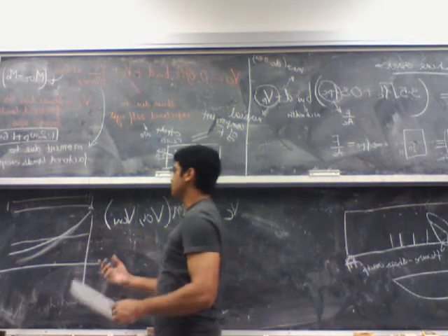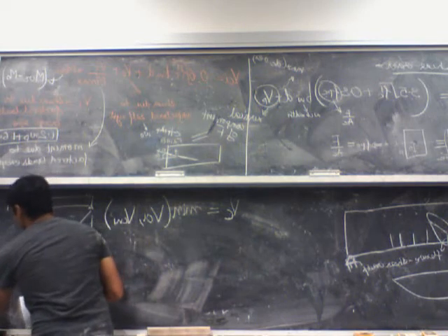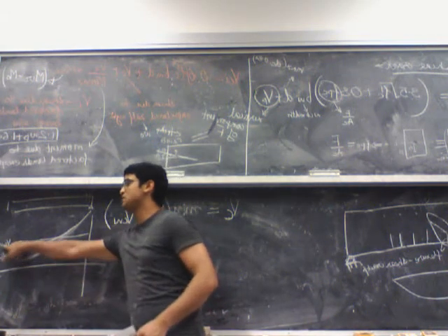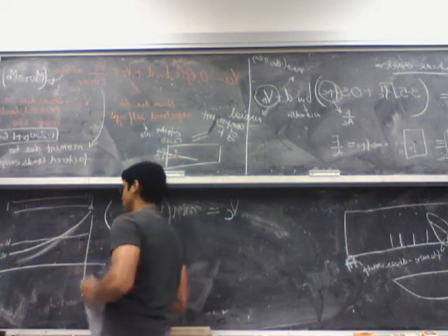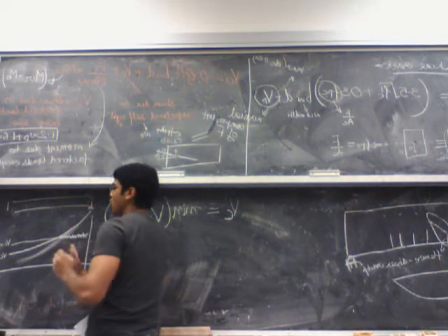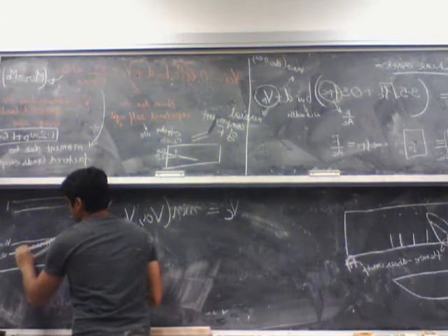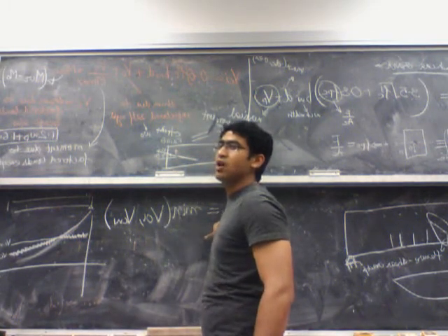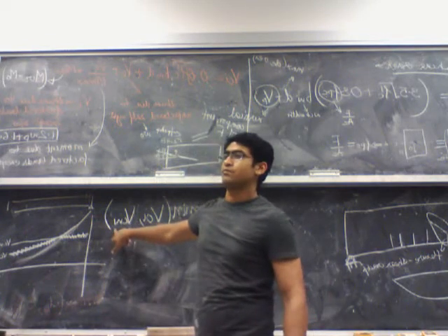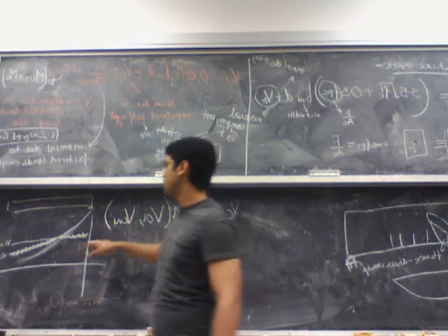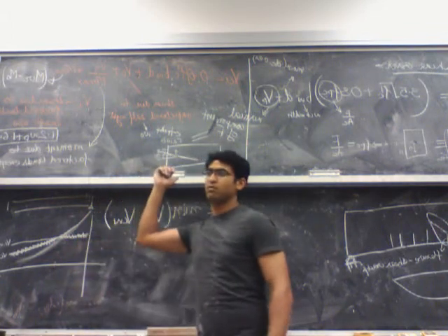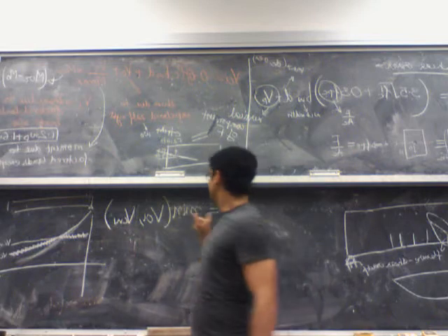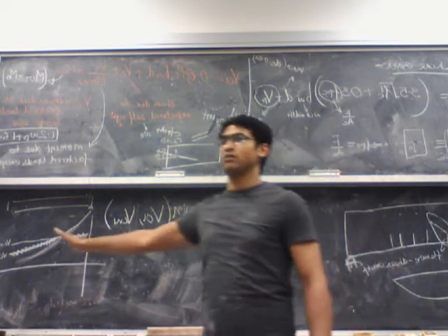So this is my VCI, this one is VCW. It is saying that near the supports, it's the web shear crack which governs my shear capacity. And as I go away from the support, it's the flexure shear crack which governs my capacity. So my actual VC, the shear capacity of the concrete itself, is the minimum of these two. And it automatically accounts for the fact that near the supports it's the web shear failure, and away from the support it will be a flexure shear failure. So this gives you the actual shear capacity of the concrete throughout the span.